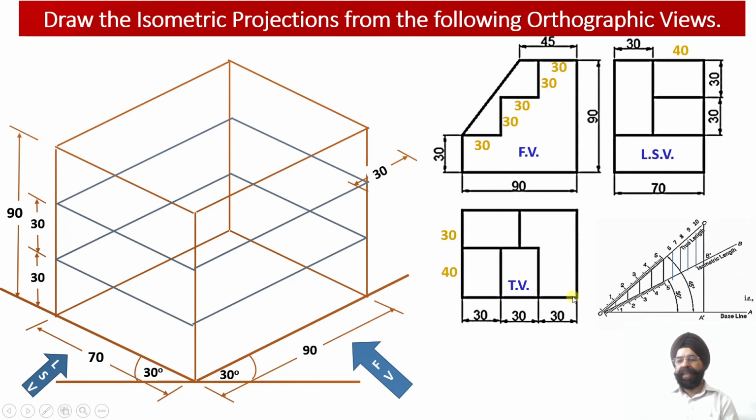I am going to mark this distance equal to 30 millimeter from the right hand side face of this particular solid. Once I mark this guidance line, I am going to mark a projection line over here which will give me information about the width of this web. But I further find out that this web is not going straight. This web is turning towards the side as I am moving towards the rear face of the solid.